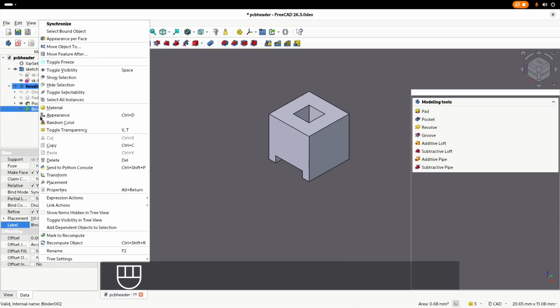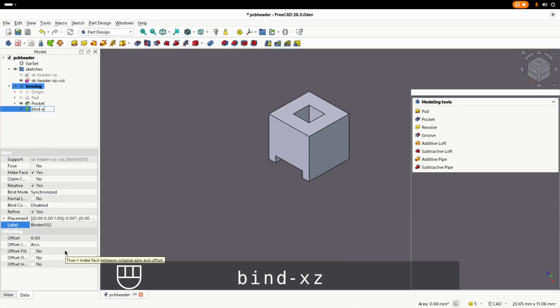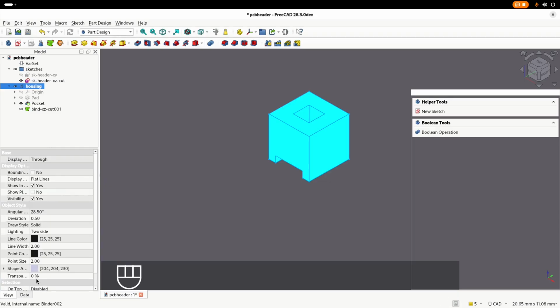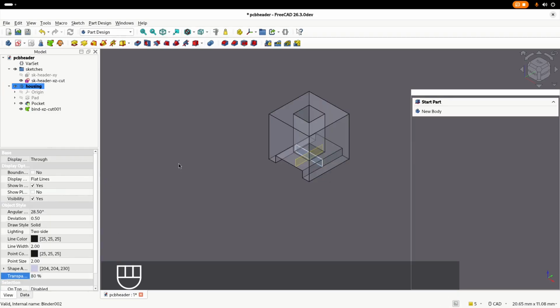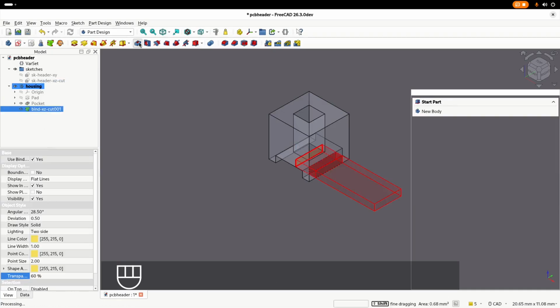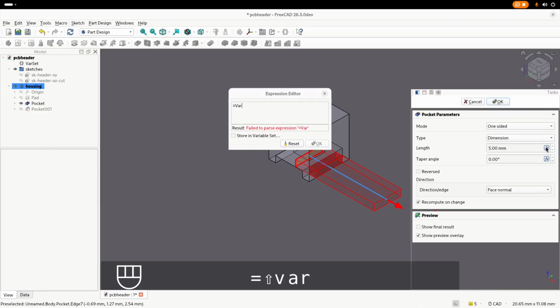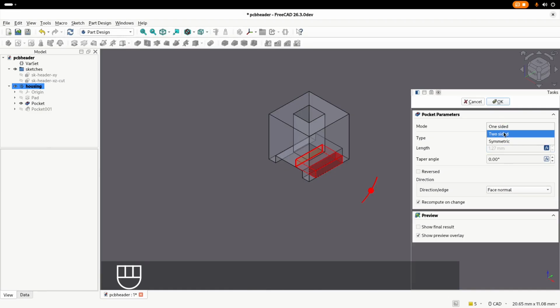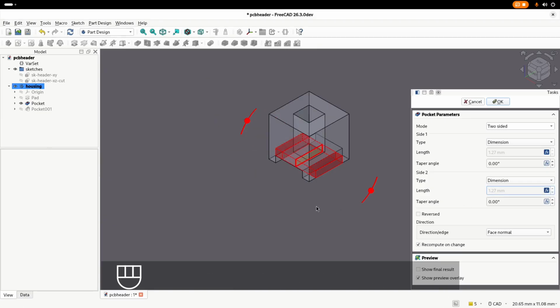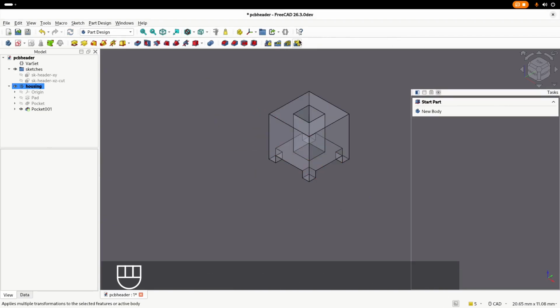Select the sketch, create another SubShapeBinder, and provide a label. Rotate this SubShapeBinder 90 degrees, create a two-dimensional pocket. Create a MultiTransform.